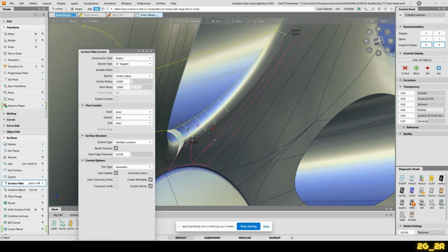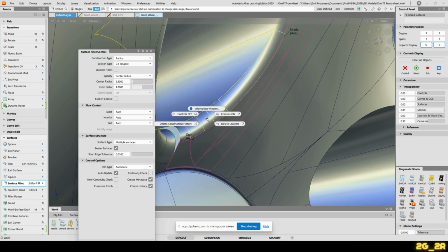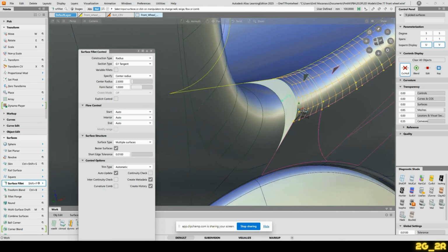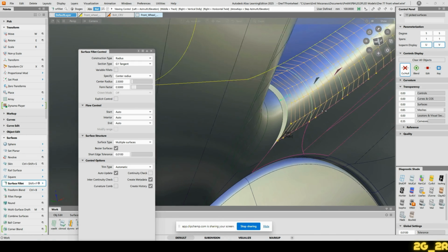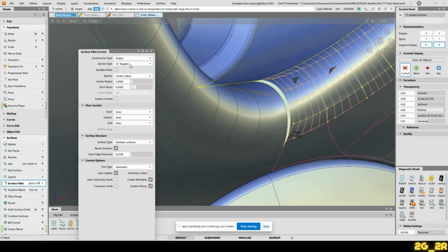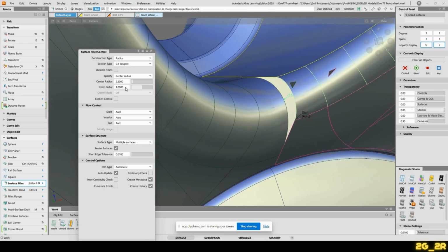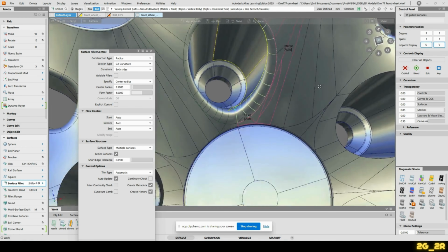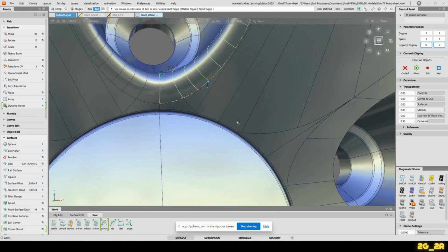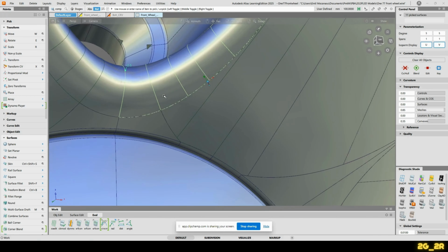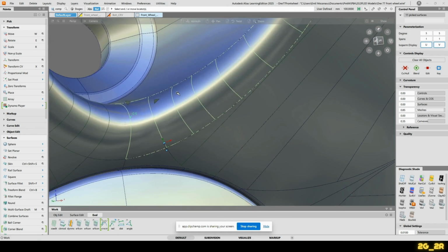Okay, let's switch this to form factor 1. And now you see this is generating an even smaller radius, meaning it spreads the CVs out differently. 0.5 is giving us this. And then let's go to G2 curvature. So now we've got the same thing on both sides. And you see we've got the inside working automatic.